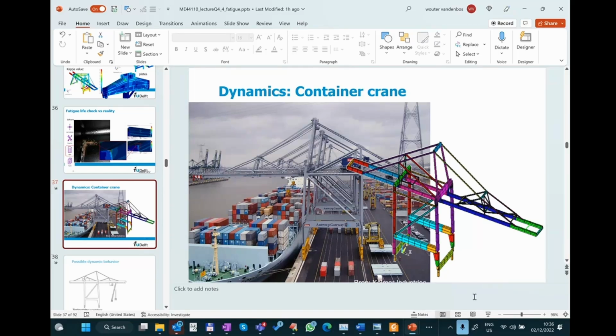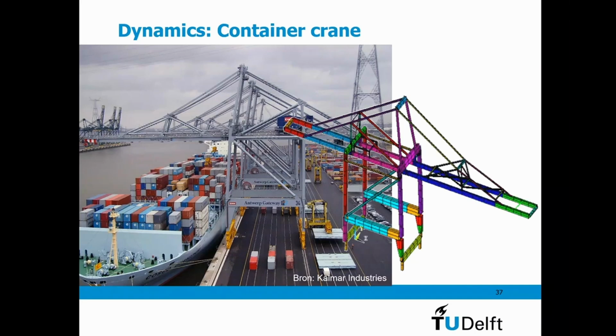We were left with the example of a crane and the way to treat load cycles, because in the old days there was not so much computer power available that you could do, like you do for example for windmills now, where you have 10 minutes of a certain scenario here, then 10 minutes of another one there, and in these 10 minutes you count every load variation.